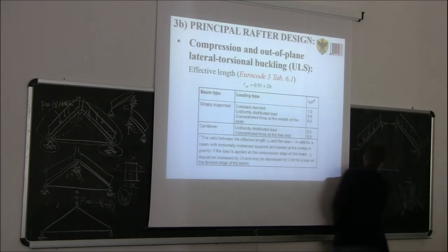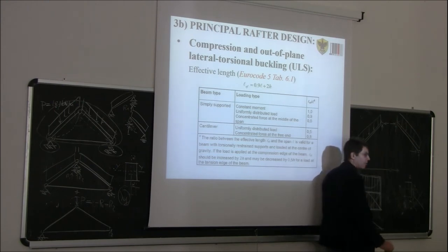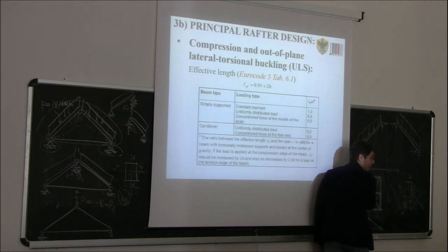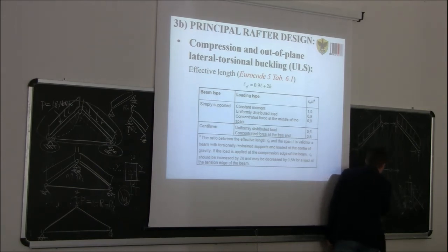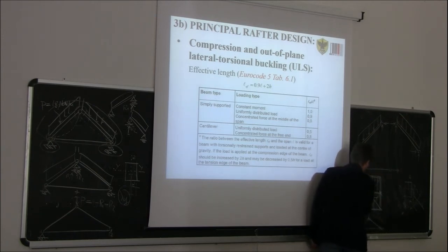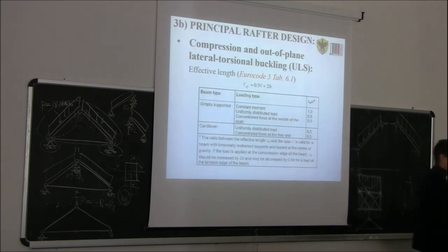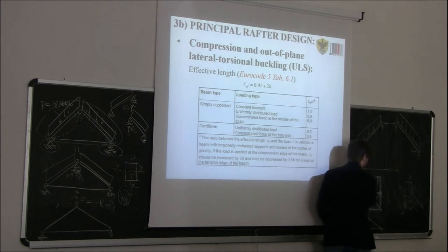So is this possible? No. Which are my fixed points right now with this cross bracing? Is this one fixed? Why not? Is this fixed? Yes. This fixed? Yes. So the deformed shape will become this one. What about this now? Is this possible? So this one is going to buckle this way. What about the other one?